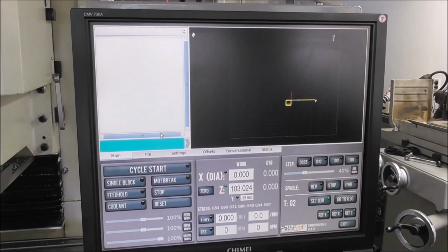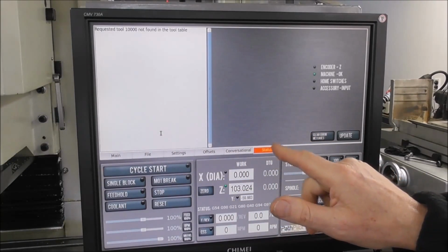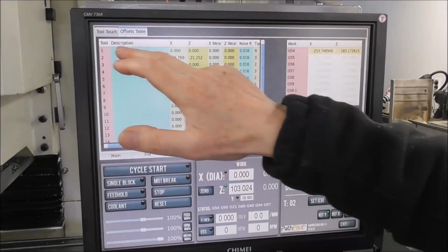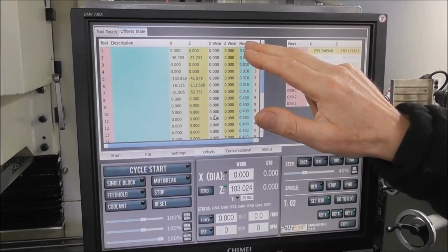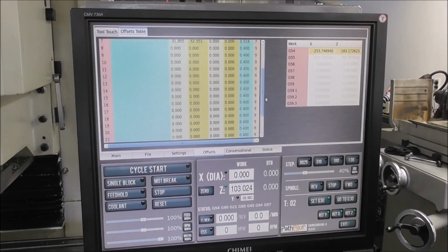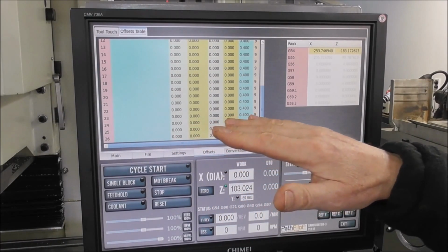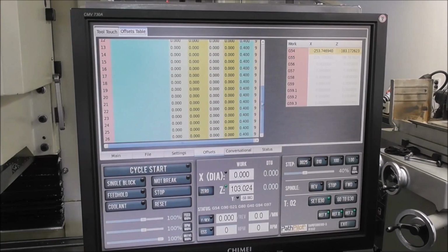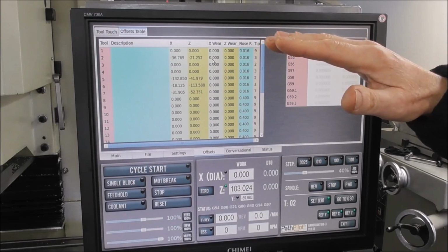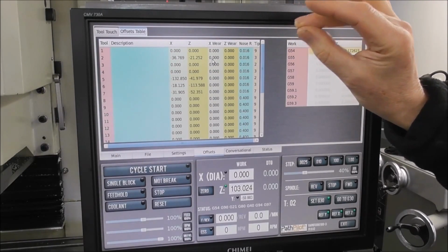And if I put in tool 0, T0, enter, we get a not found in tool table. Now that's confusing because if you're operating in mill, you can enter tool 0. Even though there's no tool 0 in the tool table, you can enter tool 0 in the mill, and that's quite useful because it will have no offsets set on it. It's a little bit like using tool 27 in lathe, and I imagine Rapidturn is the same as Slant Pro here, but I'm just guessing because I don't have a Slant Pro. Okay, so don't get hung up on which tool's your master tool, which tool has no offsets. I'm just following the example to keep it simple.